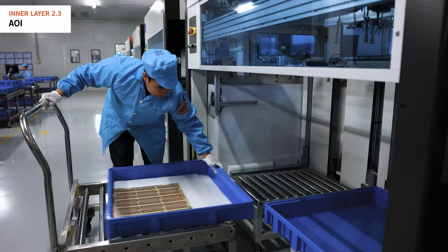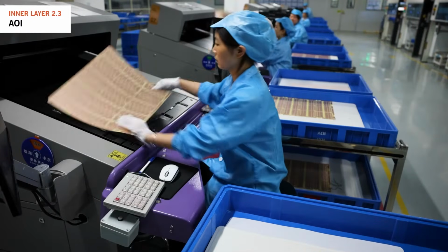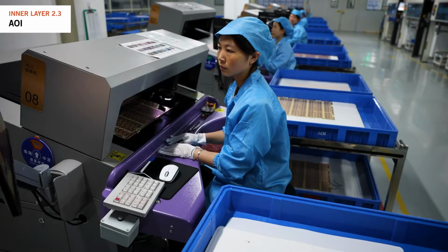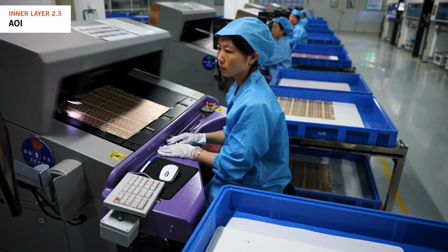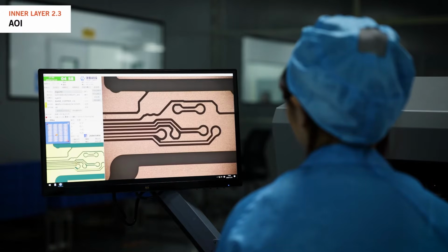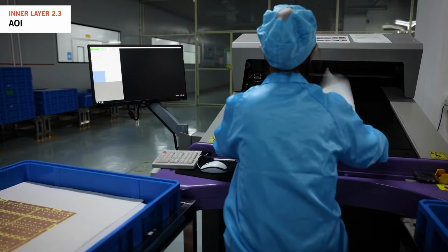The second stage is the verification stage, where operators check if concerns found during scanning are acceptable or not. They inspect the circuitry for issues like shorts, opens, or damage, ensuring that the conductor width and spacing meet customer requirements and IPC tolerances.